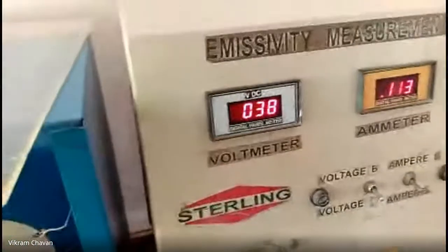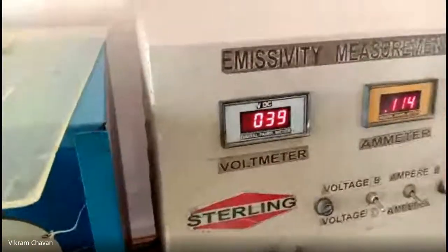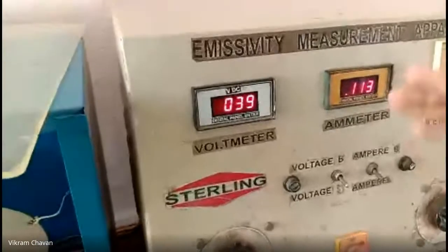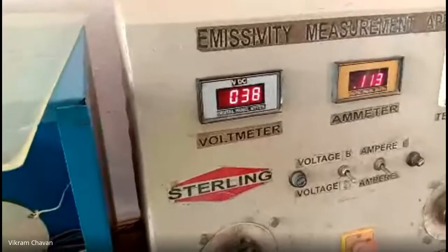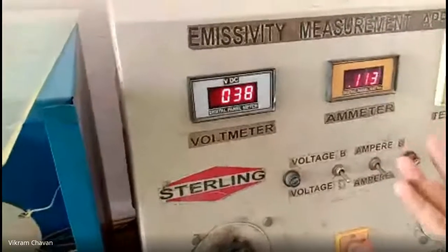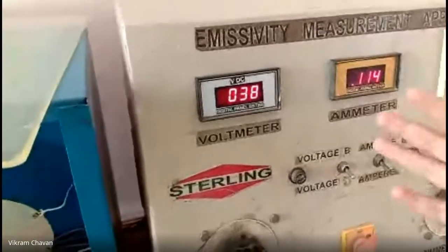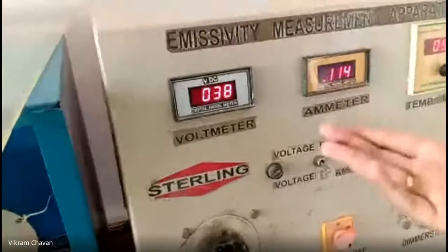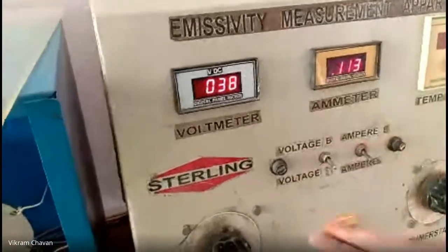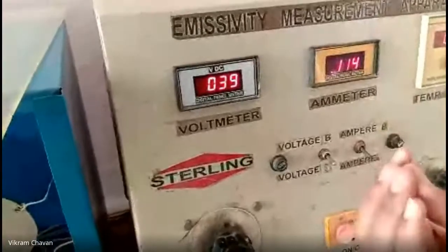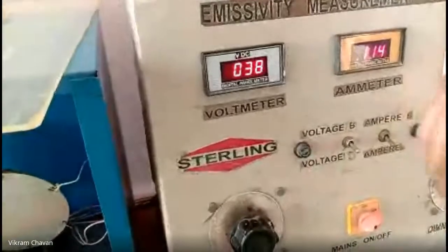Okay, so it is required that if you want to achieve the equilibrium state for both the plates, then for the test plate you have to provide less heat input as compared to the black plate. Because if you increase the heat input for the test plate, its temperature goes on increasing, because the emissivity of a black plate is high, and that will transfer the heat to the gray plate also.